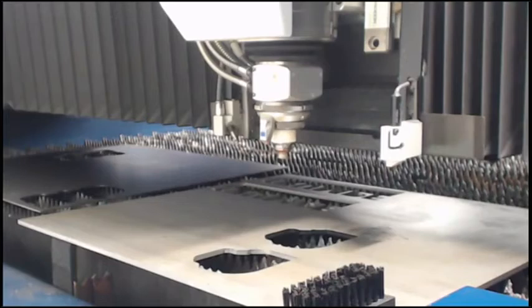So it might say, okay, I'm bringing my 2,000 inch a minute cutting speed up to 4,000 inches a minute. And even though this laser has just ridiculous dynamics, you're not going to be able to really see that translate into increased throughput because the machine's constantly trying to accelerate. So again, it could be something that is introduced in the future. And if you have one of the nozzles, you can certainly create your own tables. It's fairly easy. But as it is right now, that's kind of the practical limit we say. That doesn't mean that it actually is a limit.